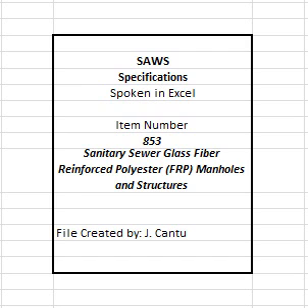A. ASTM C581 Practice for Determining Chemical Resistance of Thermosetting Resins Used in Glass Fiber Reinforced Structures Intended for Liquid Service. B. ASTM D695 Test Method for Compressive Properties of Rigid Plastics. C. ASTM D785 Test Method for Rockwell Hardness of Plastics and Electrical Insulating Materials. D. ASTM D790 Test Methods for Flexural Properties of Unreinforced and Reinforced Plastics and Electrical Insulating Materials.